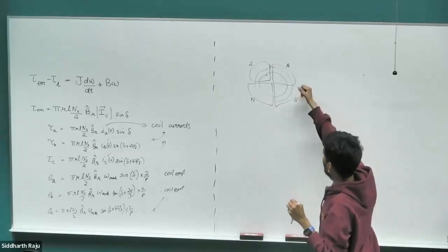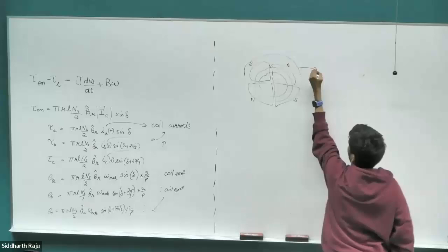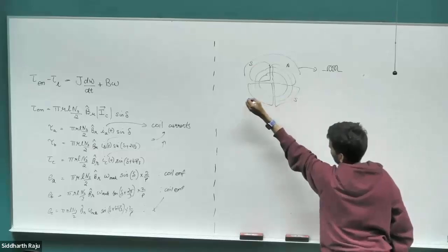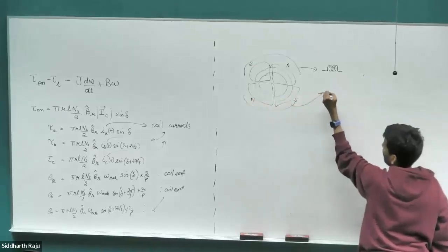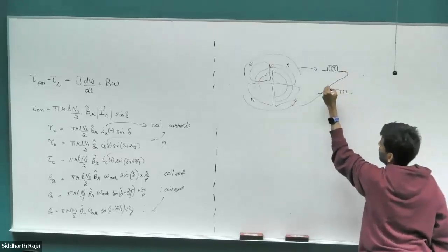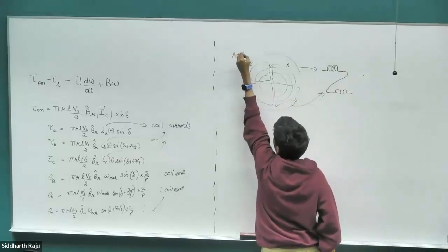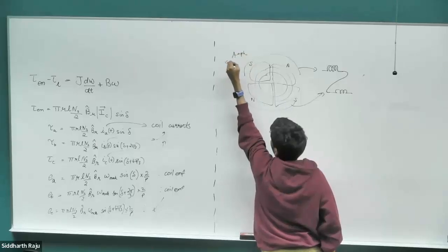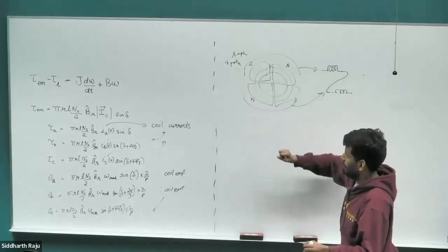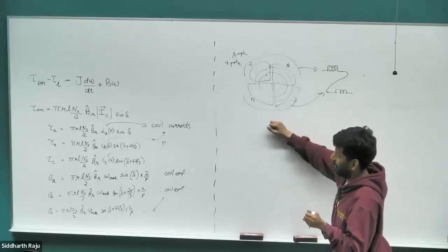Now we can represent this as one set of coil. Let me call this group. Let me indicate it with the diagram like this. That whole combined north and south together. And this group, I can draw with another equivalent coil. Now I have the option of connecting these coils in series for a single phase. So I'm just talking about A phase for a 4-pole motor. Similarly, I have B and C. Whatever you do for the A phase, you would have to do the same for B and C as well. If you have the same set of winding distribution for the B and C, it would make sense to connect them in series as well.